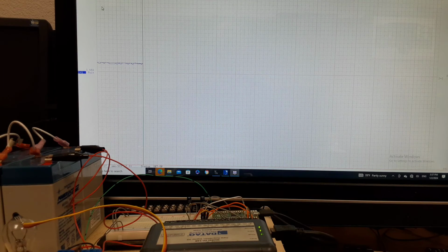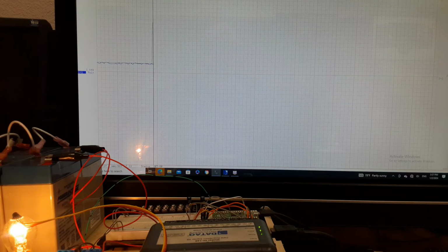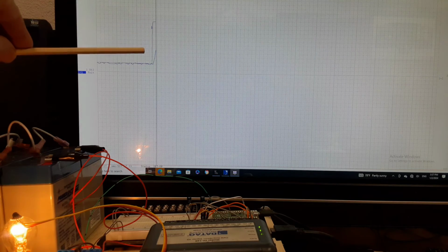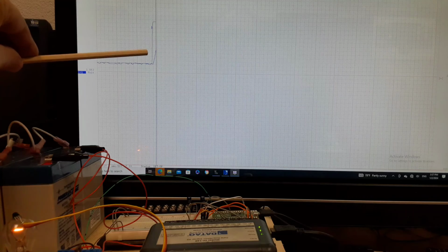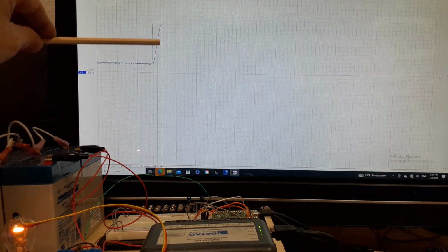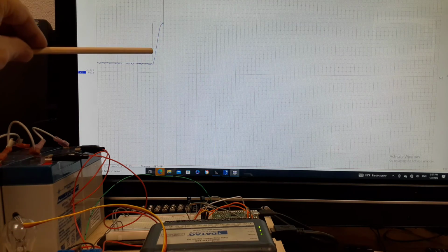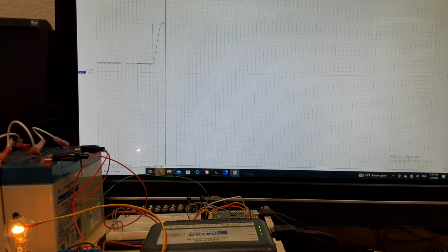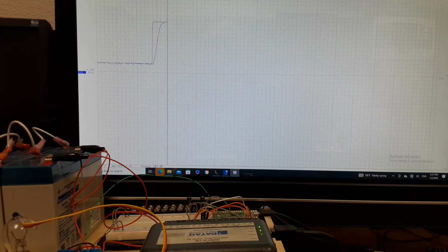So what we'll do is we'll change our set point. Right now it's at 50. I will go in and change that set point to 70, and we will see what the response of the system is then. Here we go. It's been reset. Notice the bulb is coming on to drive the temperature, and you can see the set point has come up here, and my control variable is climbing and converging with the set point. Not a lot of overshoot.